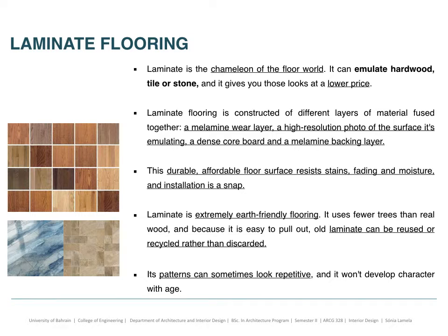Laminate flooring is constructed of different layers of material fused together. So you will normally have a melamine wear layer with a high resolution photo on the surface, emulating a specific material, or it could even be just a picture or a logo of a company. And then it has a dense core board and a melamine backing layer. It's durable, it's affordable, and resists stains, fading, and moisture. And the installation is very, very quick.